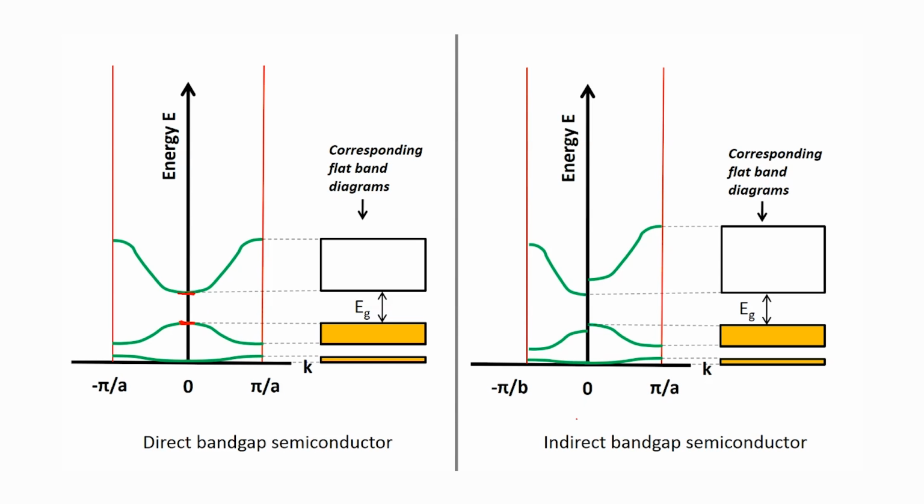Now, you look at another material on this side, and the first set of materials that I spoke to you about are called direct band gap semiconductors. Another material on your screen here is an indirect band gap semiconductor, where, if you see here, these are two different directions in K space.